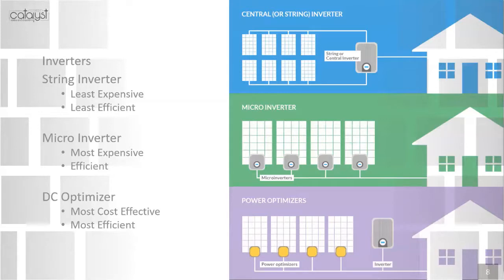The real drawback of microinverters is you've moved your failure points up onto the roof. You've got inverters up there. They're more costly. You've got an inverter per module. Whereas with power optimizers, you've got small technologies on the back of each module and a single inverter. So less money, less maintenance potentially, but the big benefit right now of power optimizers that we're realizing, if we have DC coming off the roof, is once we want to implement battery storage, I don't have any of the inversion losses from DC to AC, from AC to DC, and from DC back to AC that I would have with microinverters. So that's the real benefit.